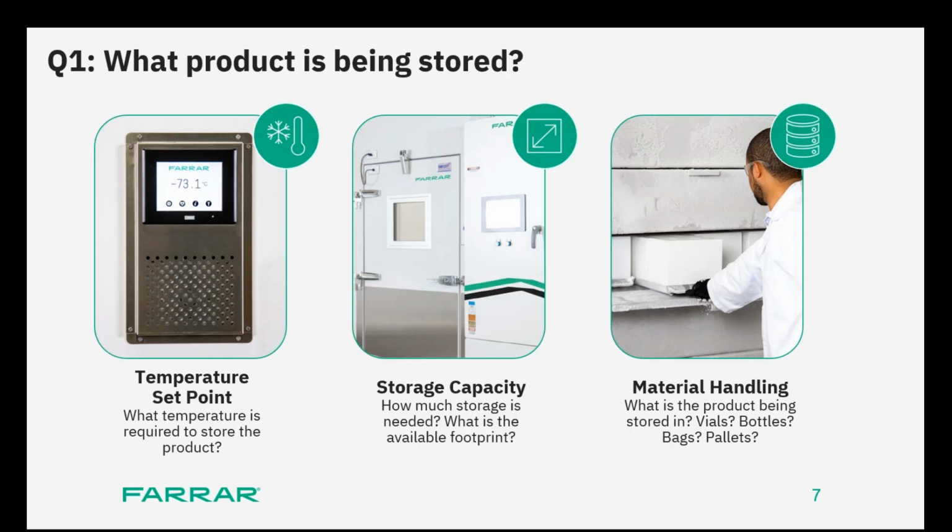After we get past that point, we are going to ask you, what is the ambient surrounding the chamber location? So where you're putting this in, what temperature ranges does your building control at? We're going to ask you what your occupation load is, or occupying load, whichever you prefer to call it. Basically, that is how many people are going to go into the chamber and for how long, so we can determine if we have to provide makeup air per OSHA regulations and safety for people. And then we want to know how often you're going in.